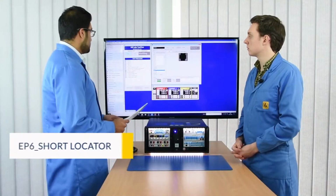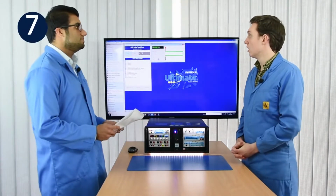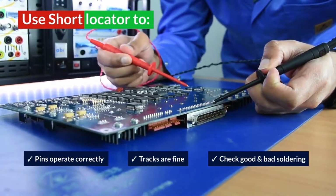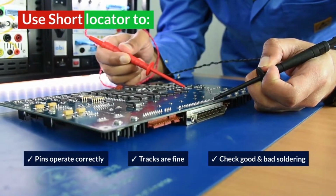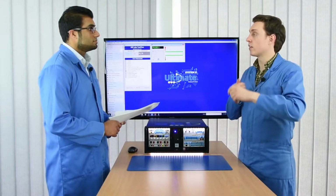In episode 6 we covered the short locator. So it's a very simple test, however it can be used in many different ways. So what can you tell us about that? So we did this episode on the short locator, and we demonstrated the different functionality of such a simple instrument. Yeah. So one case is that you can use it to find the VCC on an IC. If you know the power rail on your PCB, you can go across each one of the pins on an IC and find which one's VCC, and then simultaneously do the same for ground.